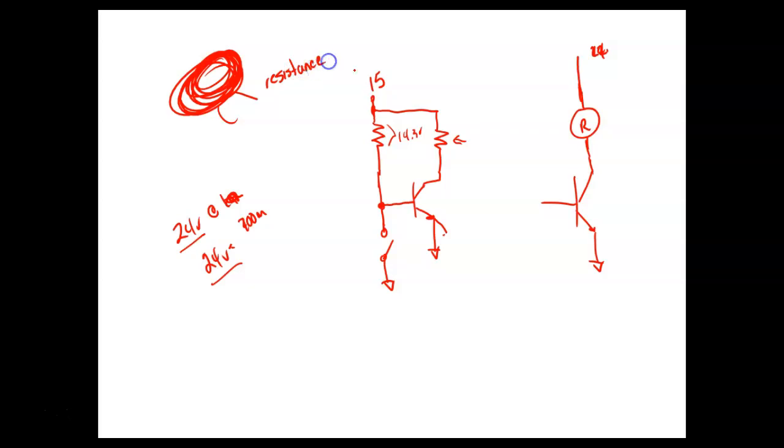So DC relays are going to have a lot of turns of wire. Anytime we put current through a conductor, it sets up a magnetic field. And if you have conductors going through, your magnetic fields combine. Now you've got all these turns of wire out there, and then you turn this relay off. Well, that magnetic field comes collapsing down.